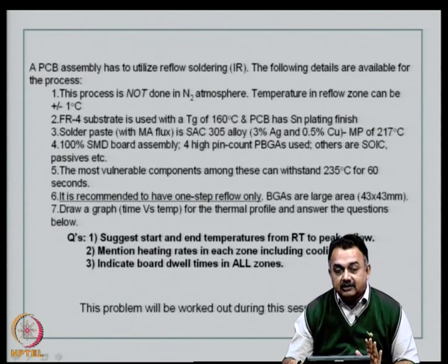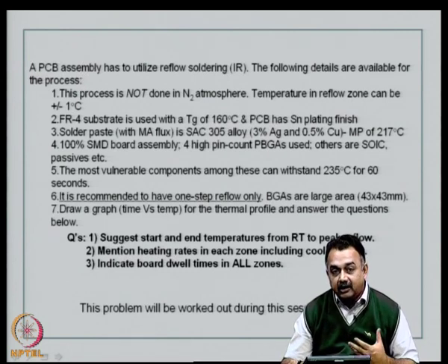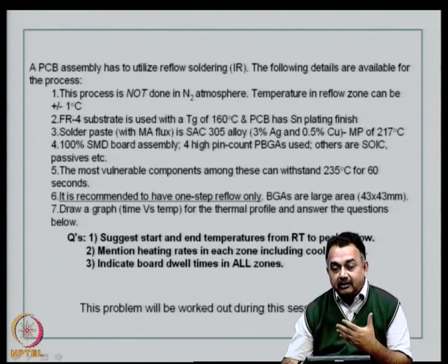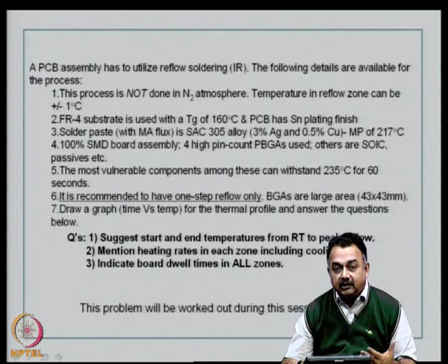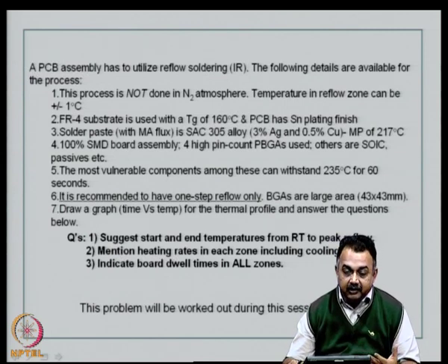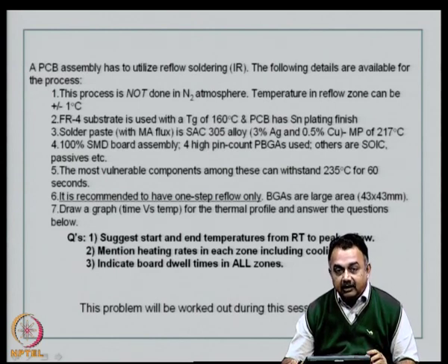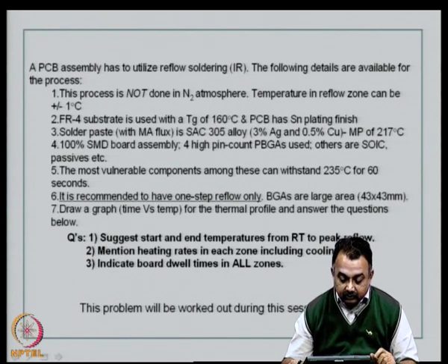The reason why I am giving this information is that if you have high pin count PBGAs, let us say there are 800 solder balls to be soldered, then you have to give more residence time, okay, for all the flux that is being used under the plastic BGA to get activated. You must also consider giving more residence time at the reflow zone, so that you will not end up with a plastic BGA where 30% of the solder balls are not at all attached or reflowed. Okay. So, make a point about this.